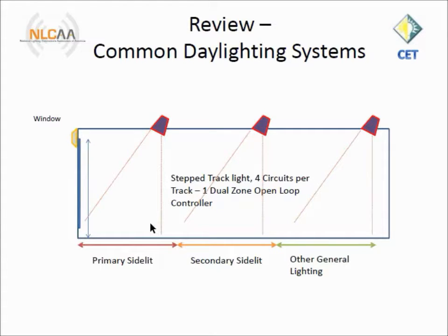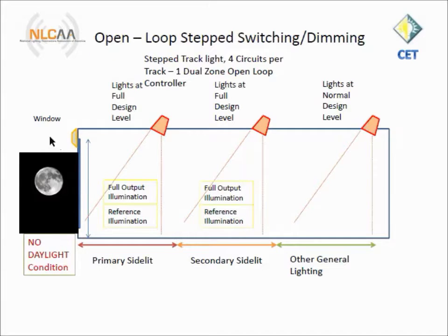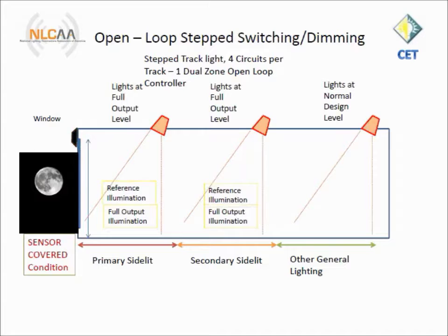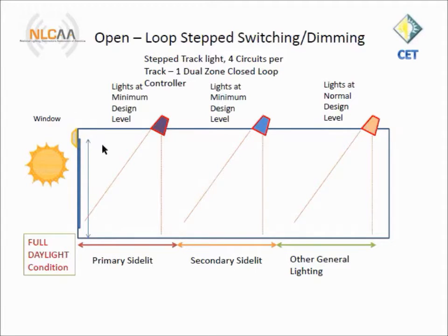So the very first thing that you do when you set up an open loop system is tell the controller what the ratio is of what it is seeing under daylight conditions outdoors versus what it is seeing at a particular spot of interest, a task location, and sometimes the reference location, which is a special task location within the zone illuminated by the control luminaires that we use to do acceptance testing and that commissioning agents use to set up the daylighting system.